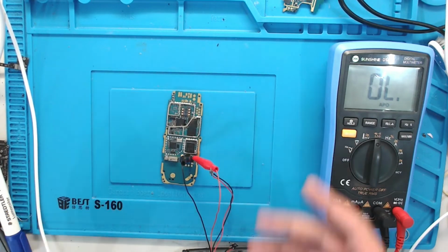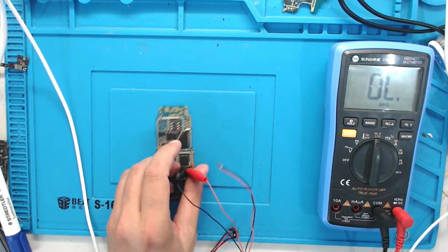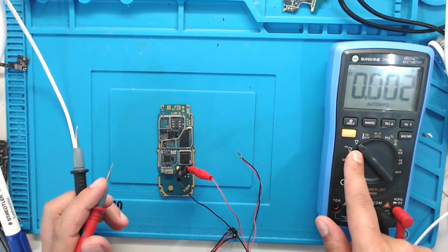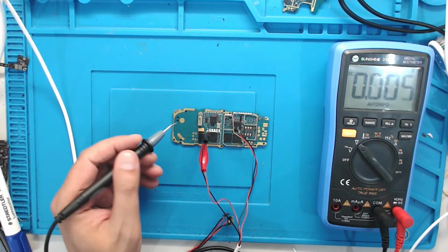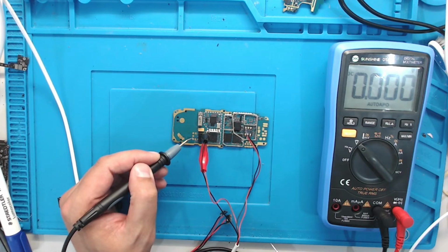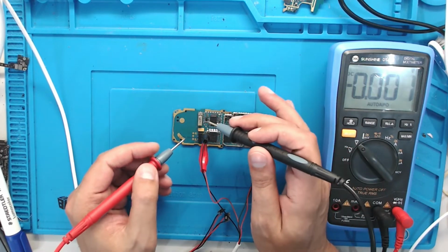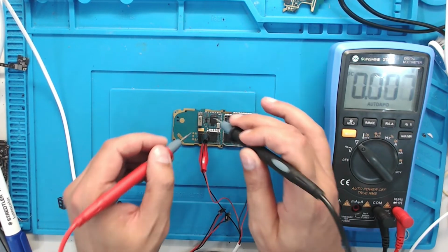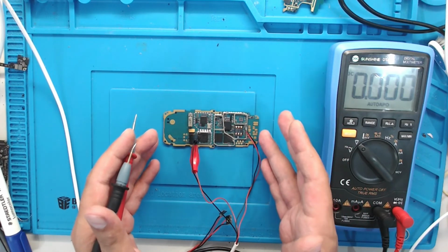Yes. Now bring the 4 volts voltage to this phone. I've set up the multimeter on DC voltage, and you see there is a golden circuit in there for a test point. First I check whether there is 4 volts inside the phone or not. This is the best and safest voltage from the DC power supply.